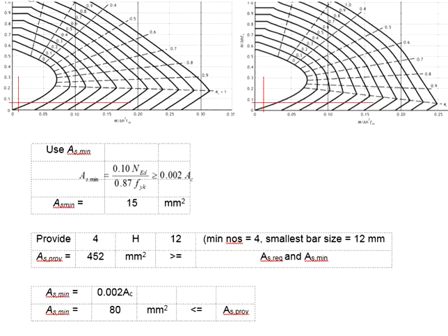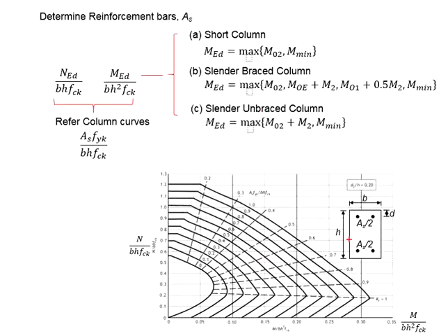First, for a typical column design, you will need at least 4 reinforcements, 1 at each corner. Why is it so? These 4 reinforcement bars shall later be tied with the shear link. Therefore, bare minimum 4 reinforcement bars.